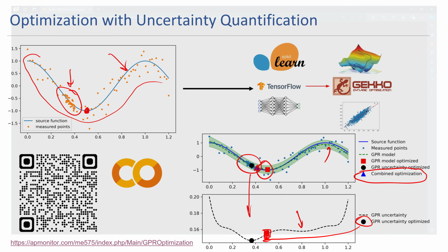All right, so here's a dynamic simulation. I'll create a dynamic simulation just based off an image. So I've just uploaded an image of my process, and I want to be able to generate a simulation of this. It's going to generate a simulation of this 2-tank system with a pump and a reservoir. Now this is just from the image that you see on the right there, and there's a QR code to take you to that. You can try it out as well. Just go ahead and upload that image and ask it to develop a Gekko simulation of that system.